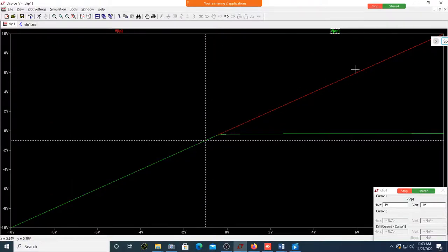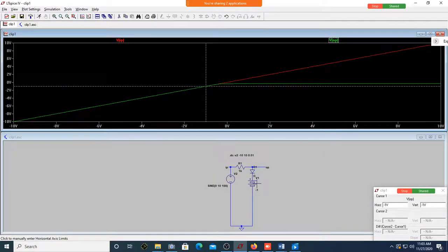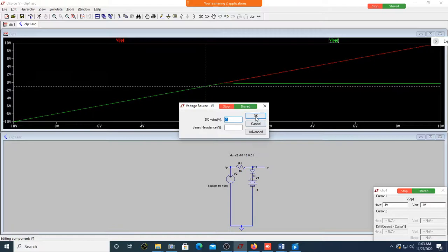This is the reference. Reference is input because you have input over here. And this is your output voltage. Can you see the output voltage is following for negative voltages? And of course, because you have a reference voltage of minus 1, till minus 0.3 it is following. Afterwards it is minus 0.3. This is as per this circuit. Correct? Yes, sir.